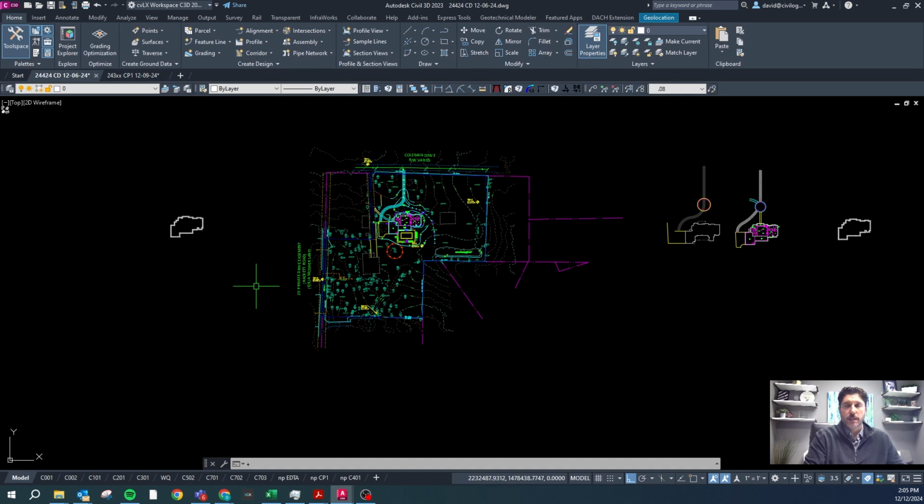This is a residential project. We've already gone back and forth with the client to get the house situated and elevated where they want, and we want to see what the earthwork takeoff is to see if we need to make any adjustments. We've skipped over the conceptual takeoff for this project because it was more important to get the house and everything situated the way the client wanted, but typically with a commercial project we'll do a conceptual takeoff, which is way more rough and just makes sure that we're ballparking the finished pad at the correct elevation. So let's get going with this preliminary takeoff.